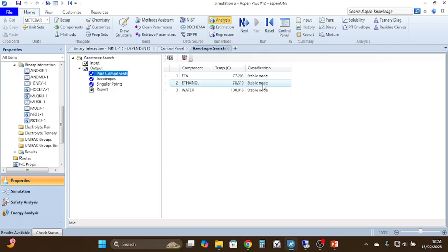In that case, the process is said to be in the steady state. For example, if you are heating a tank and the temperature you are measuring has reached a particular value and for a time period that value has not changed, and the system is also not disturbed, then we say the process has reached a steady state.